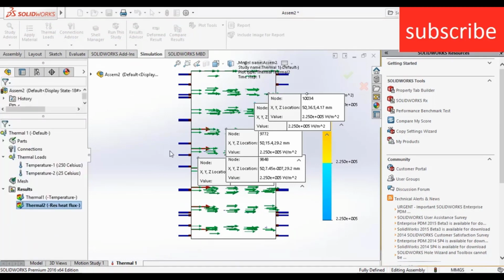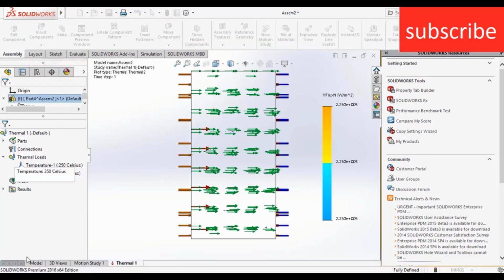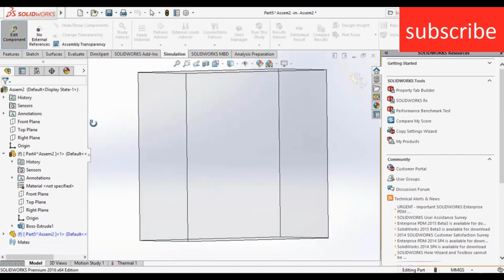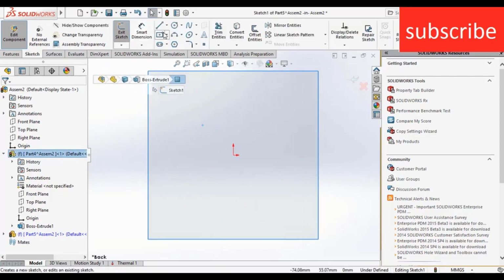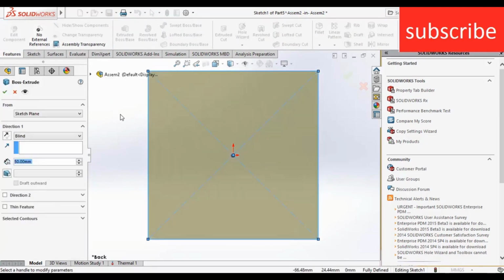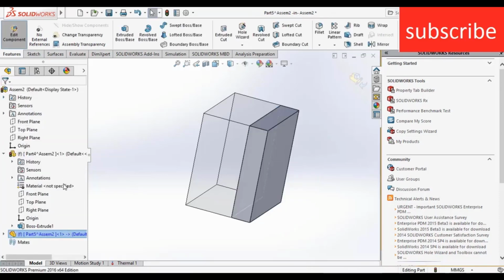Now let's talk about the composite beam. To do a composite beam, first go to assembly, click on insert component, click on new part, go to model, select this part, go to assembly, click on edit component. Now select a face, click on sketch, press Ctrl+8, draw a square, and extrude it as per your requirement. It is not necessary to do what I am showing here, you can do the same. Enter 20 mm, click OK.